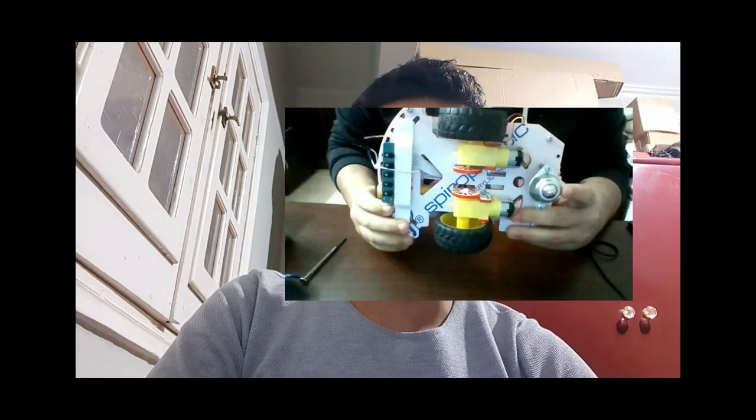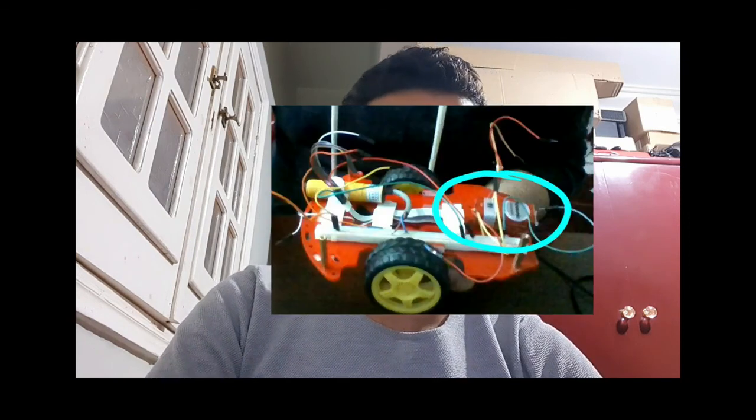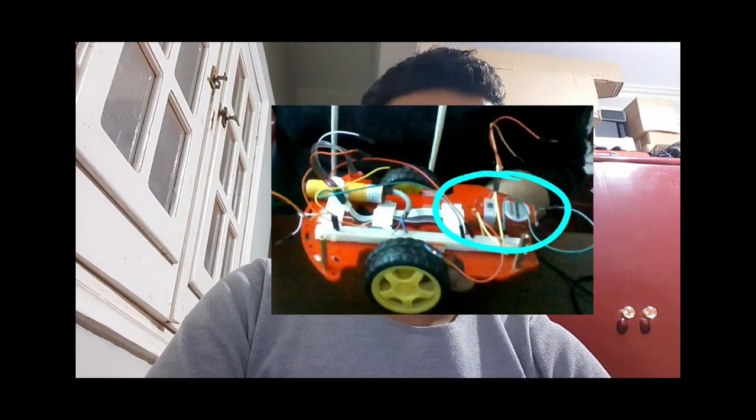Hi everyone, my name is Mahmoud Hisham and I'm here to talk about one of the problems we faced in our project. We had a balancing issue with our car. We had two motors in the middle, two sensors in the front, and only a caster ball at the back. So we needed to put some extra weight at the back to balance things off. And for that we used extra batteries, just as dead weight, and that solved the issue.